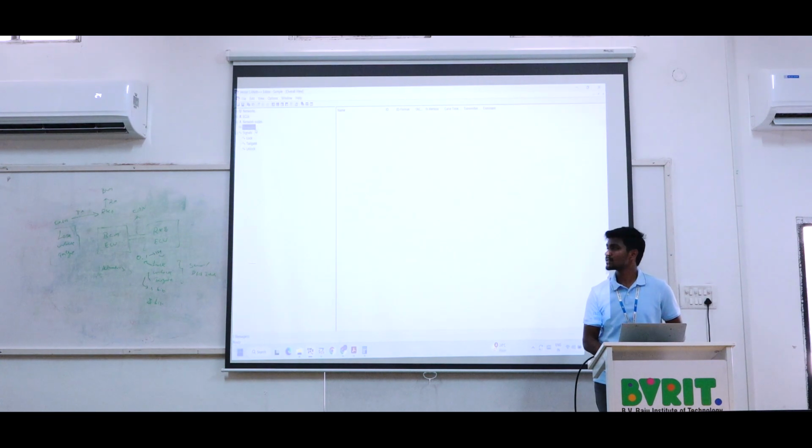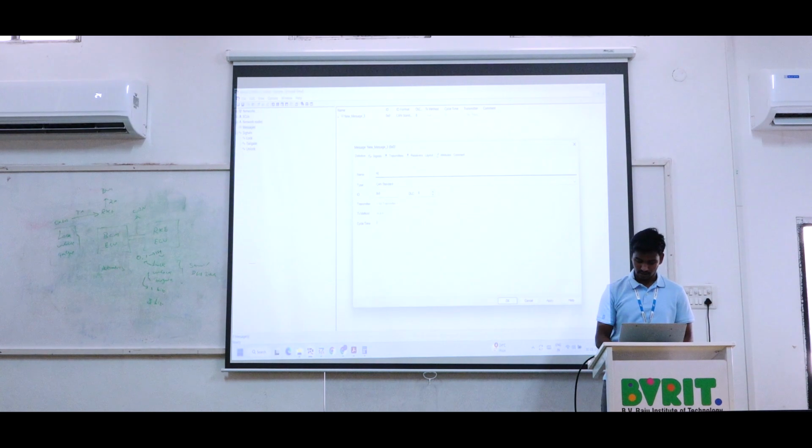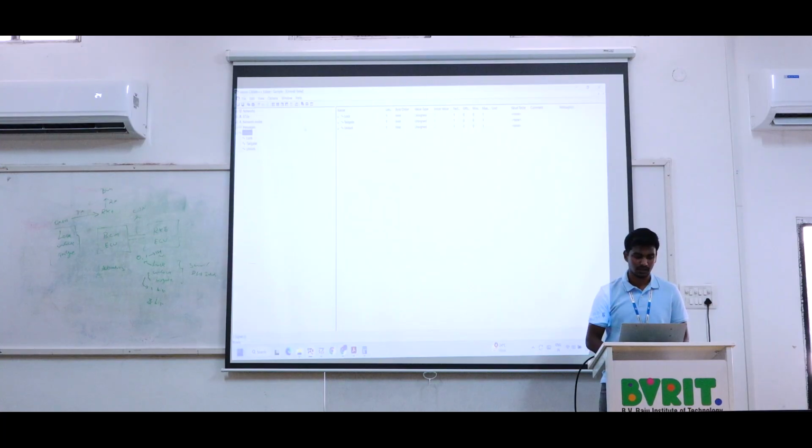Shall I put messages? Yes. So in the message column, you right click, new message, Control A. I can mention it as RKE_1, with ID number 4. Apply and then OK. So in signals also it is showing the X marker, and the messages also show the X marker.